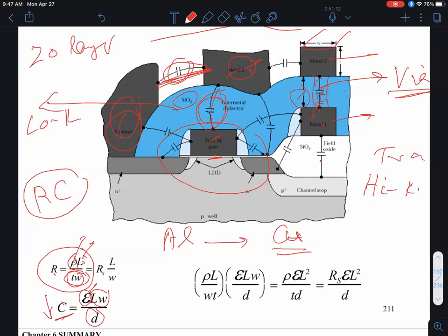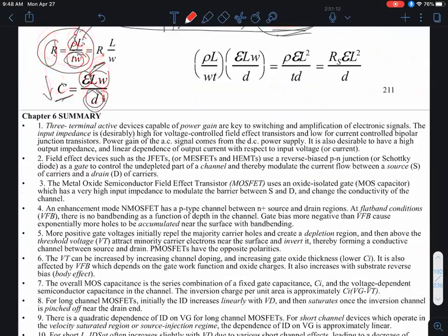Okay. You also want these thicknesses, D, to be as thick as possible. But there's practical limits to that, because if I want to make a very, very thick dielectric, it will take a long time to deposit, and then you have to etch contact holes in that. So there's limits as to how thick you can make D. You want the epsilon to be as low as possible by having low K. You want the resistance to be as low as possible by having as low resistivity of a metal, and that's what you have in a modern IC today.